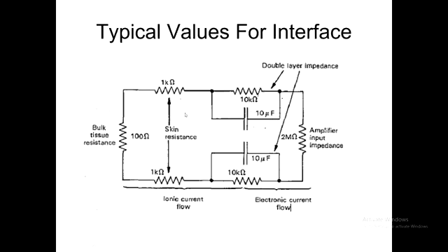So all this other junk, all the other resistances that sit around it, effectively we can see that they're kind of in parallel, except they're kind of in parallel with this capacitor too. So those resistances in parallel will form an equivalent resistor for that capacitor, defining therefore a time constant, and the reciprocal of that time constant will define the break frequency.